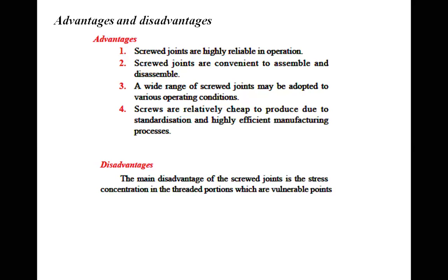Basically, in the screw joint, we have to drill a hole. When we drill a hole inside any sheet or any material, and if that material is subjected to forces, obviously there is a possibility of stress concentration. So that is the main disadvantage of screw joint. The screw joint has stress concentration.